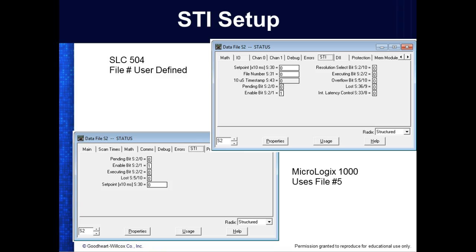And then we would put the file number in S:31, so it's a 16-bit register, right? On these registers, if we don't specify a word, then it's going to assume a word, right? Y'all understand what we're saying? So of course, inside our counter, we have to specify a word. But if I'm specifying a register, if I just put S:0, it's going to use the one. So the set point is an S.